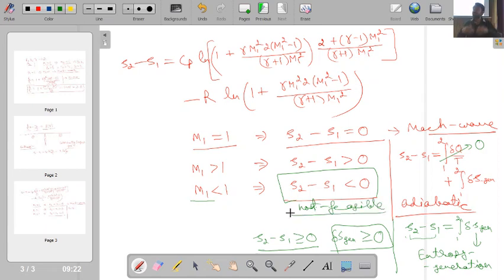Okay, so this is interesting to note that mathematically we have understood that when our Mach number is less than 1, then flow is nothing but subsonic. So when we have a subsonic flow situation, we do not have the presence of any shock wave. Physically also, by taking the help of the entropy equation, which means the second law of thermodynamics, we get that if my Mach number is less than 1 and I say a shock wave is present, then I get the entropy generation term as less than 0, which is nothing but a non-physical situation.